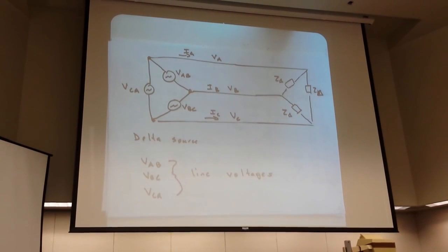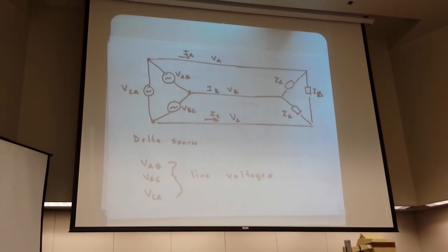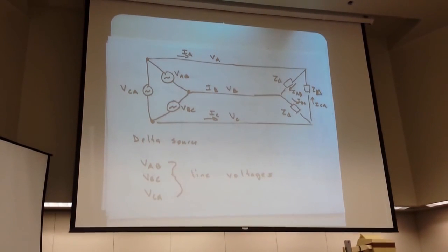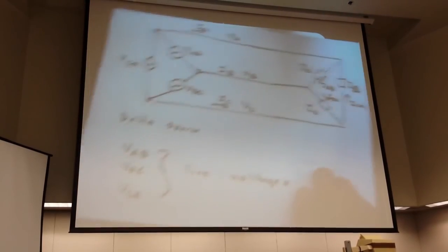Well, with this in mind, we have these line currents and these phase voltages, and now we know the voltage across this, VAB, in this case VBC, and then VCA, and so we have a current here, IAB, IBC, and ICA. And so that's again a circulating current oscillating back and forth in this load configuration. And so, how do we get this? This is Ohm's law again.